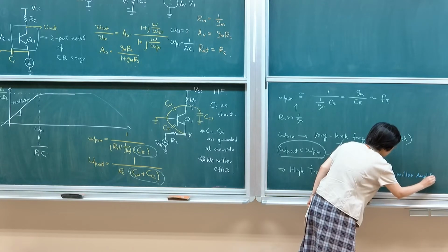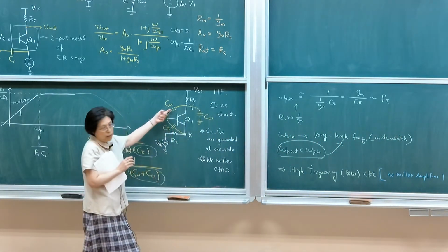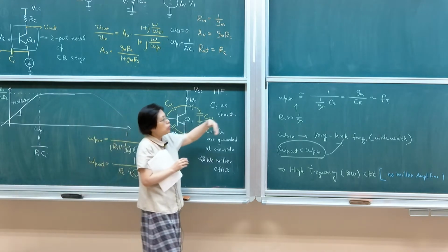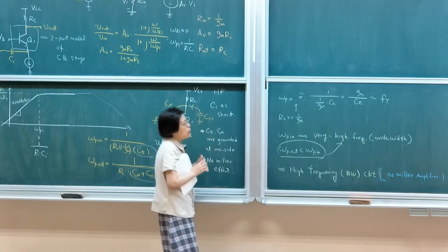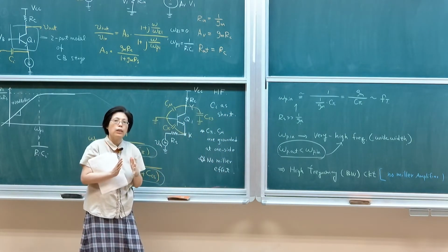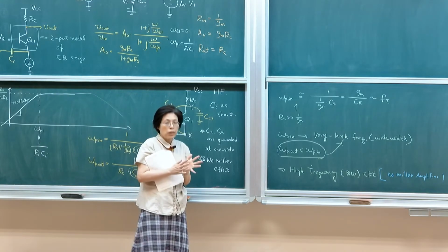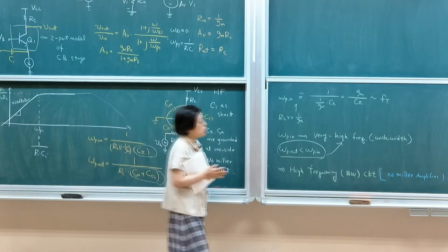So whatever your capacitance is, whatever parasitic capacitance would then dominate, that would then lead to your ultimate circuit limit. That's your fT. So the bandwidth of the circuit would naturally approach the intrinsic frequency, the intrinsic transit frequency, or intrinsic bandwidth. Okay?